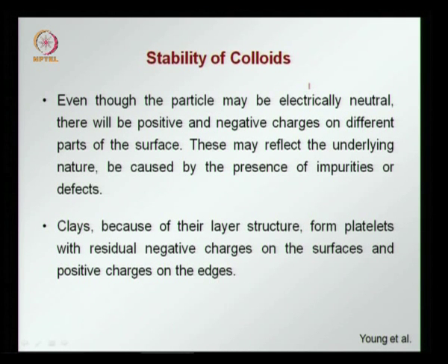So as we said, even though the particle, say in this case a clay particle, may be electrically neutral, there will be positive and negative charges on different parts of the surface. This may be due to the nature of the surface, the impurities and the defects that are present on different parts of the surface. Consequently, clays, because of their layered structure, form plates with residual negative charges on the surface and positive charges on the edges, which gave rise to the flocks that we saw in the diagrams in the previous slide.